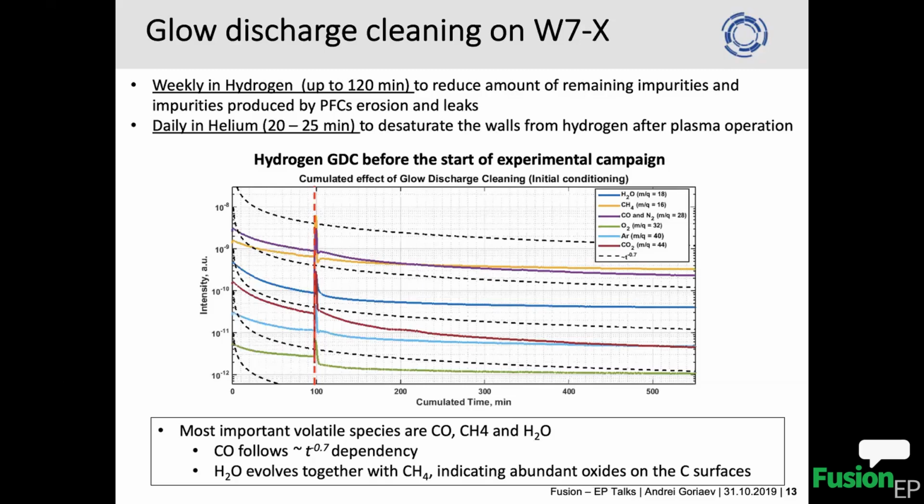And glow discharge cleaning with hydrogen effectively removes all the impurities which you can see in the sketch. It's necessary to apply it for a certain period of time to remove the impurities further after baking. Baking will not solve all your problems. Baking is really good for start vacuum conditions, to reach high vacuum.